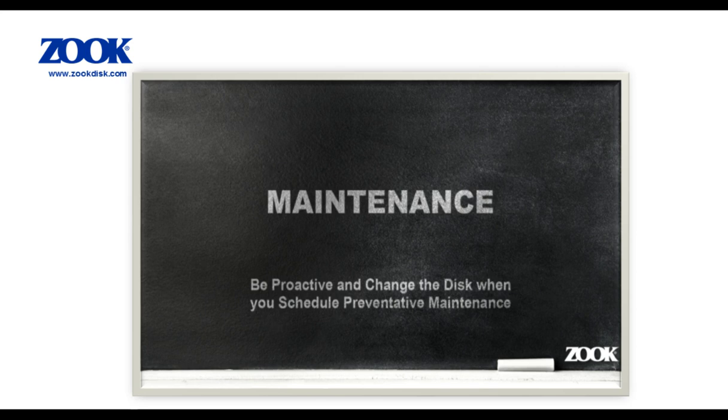People ask us all the time, how long will my rupture disc last? The truth is, nobody knows, and scheduled preventative maintenance is recommended, or when the process is already down, change the disc out. In the absence of actual installation history, we suggest starting with 1-year intervals between scheduled maintenance disc replacement. I understand how self-serving this sounds, but if you want to get out in front of it, be proactive. The cost of replacing a relatively inexpensive disc is far less than the cost of an unplanned shutdown and the resulting loss of product and production.